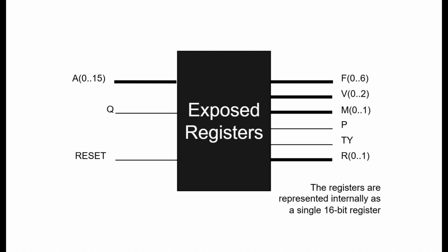For example, the CPU clock speed is controlled by a 2-bit register, R. This needs 4 addresses, FFD6 to FFD9. The first 2 addresses control the first, lowest bit of the register. The second 2 addresses control the second bit. This is somewhat cumbersome to work with, but without a data bus, there isn't much option.